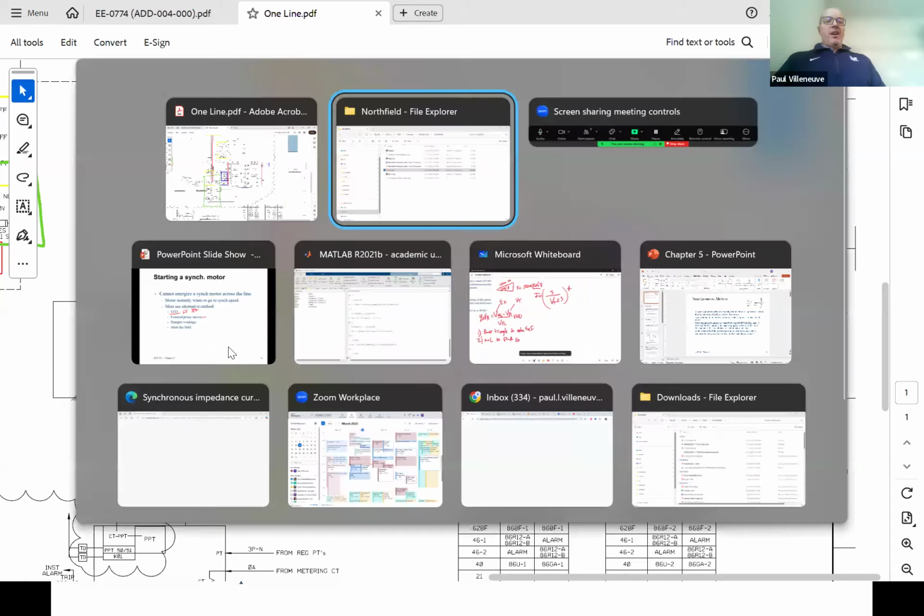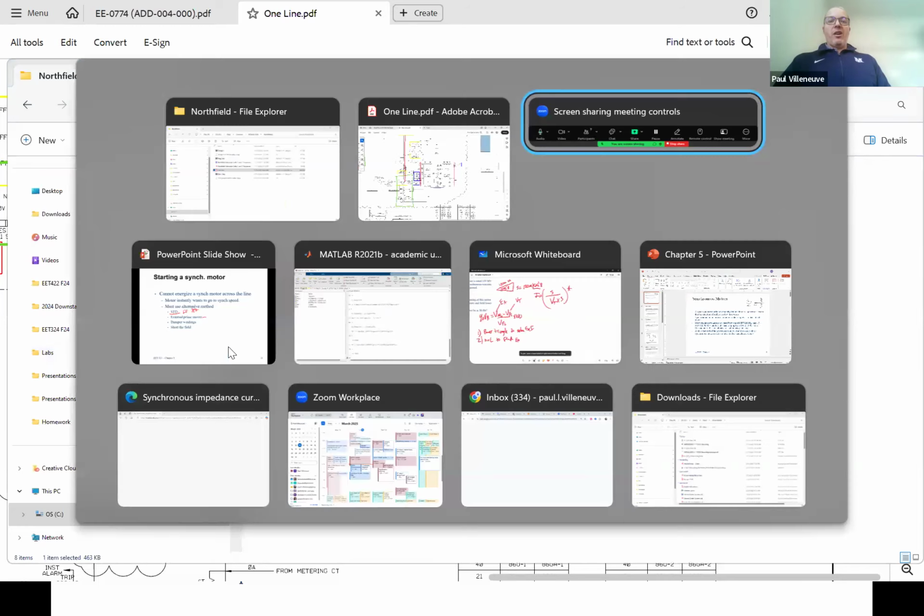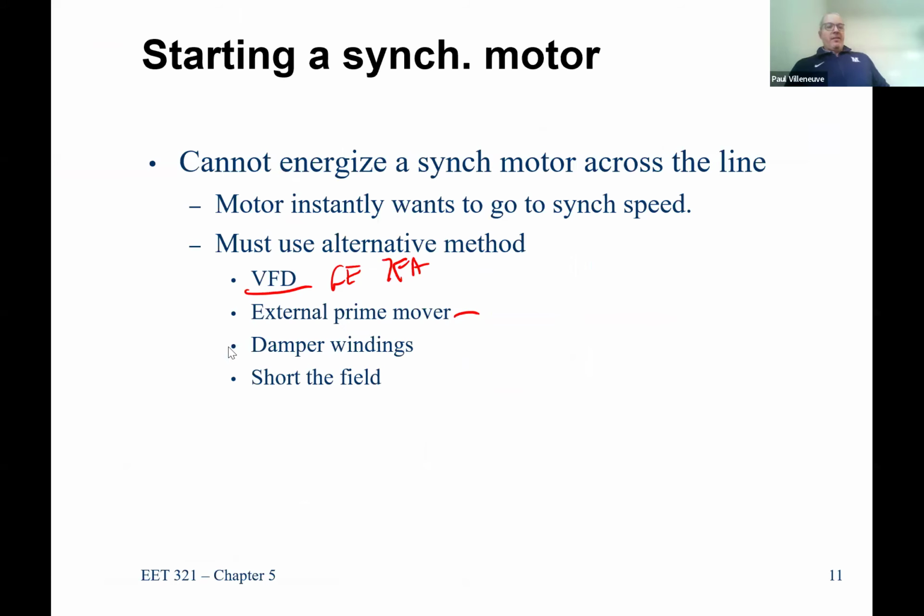So that's another way that you can start a synchronous machine. There are a second set of windings on the stator windings. They're called damper windings. They help smooth things out. Sometimes you can start them like that. The third option is to treat it as what we call an asynchronous or induction machine, which is exactly what we'll be studying when we move into the next one.